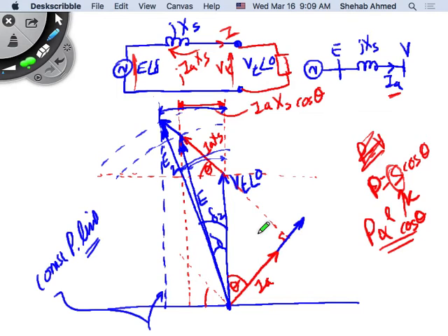So generators are the same. What will be the effect of heat? The heat is the current flowing through these windings. So there will be a limit on how much armature current the generator can supply. This armature current will cause some voltage drop across the impedance of the generator.